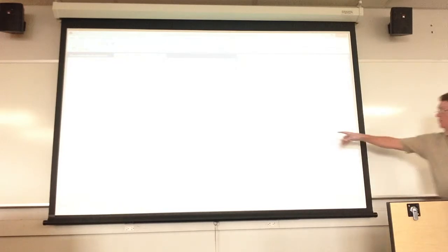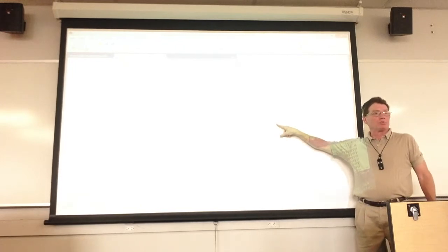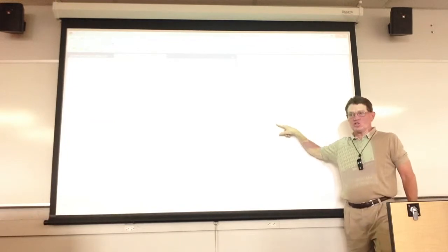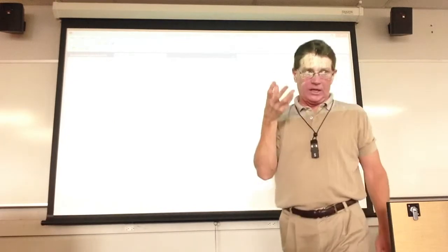Now we're going to read those pins. We're going to read them in, so I'm going to IN into R16. Now, if you look, let's go over here to the processor view. Go to the processor view, come down, and you'll notice that the 8.5 that was written to port C now resides in R16. We have simulated this.